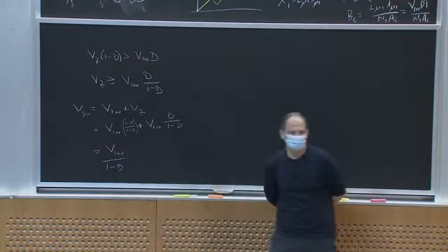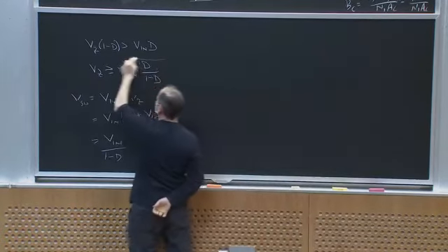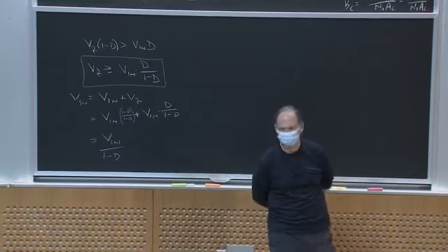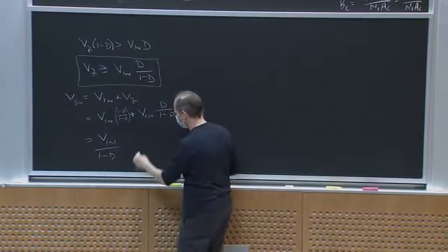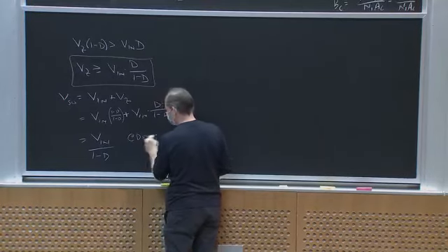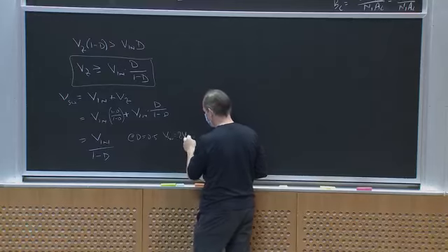So if I pick a big enough Zener voltage to get the 0 volt seconds balance on my transformer, I get this voltage. At D equal to 0.5, that would give me V switch equal to 2 Vn.